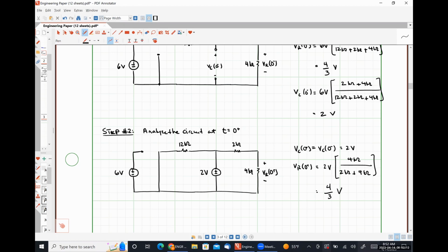It's going to work out like that in this particular case because those resistors are in parallel with a capacitor. And since the capacitor voltage couldn't change, the voltage drop over that combination of resistors couldn't change either, but that will not always be the case. So for this specific circuit, it works out to where this voltage didn't change. Okay. All right, so anybody have any problems with the analysis that we did here at t is equal to 0 plus? Fairly straightforward, right? Okay.